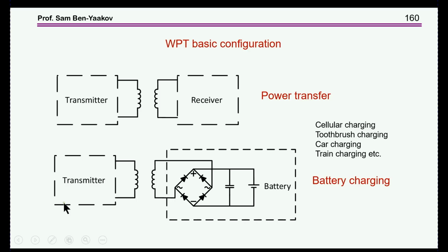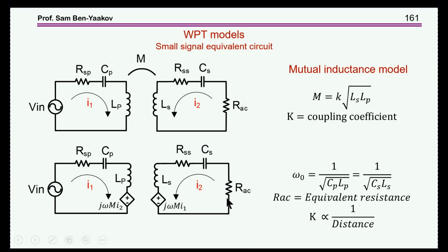Basically, we have a transmitter, we have a receiver, two antennas, and then we have, one way or another, usually a rectifier, because we need DC for various apparatus, various circuitry that we have. But we might have a converter here too, I'll talk about it in a minute, and a battery. Now, to maximize the power transfer, we do what Tesla did. We tune the two circuits. We tune the primary, the transmitting antenna, and we tune the receiving antenna.